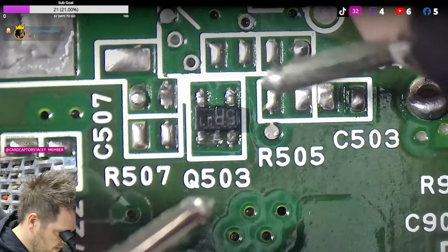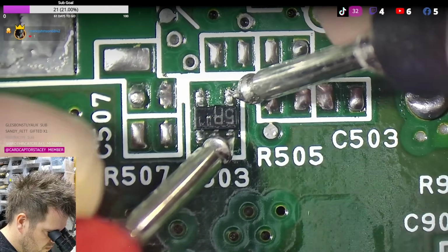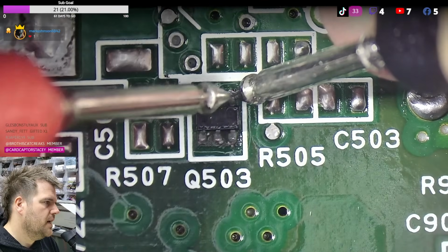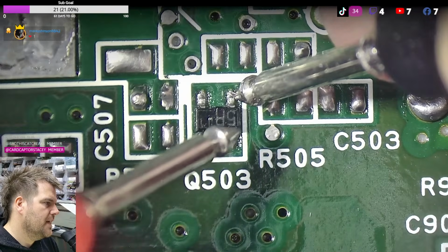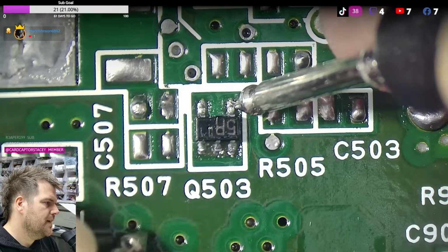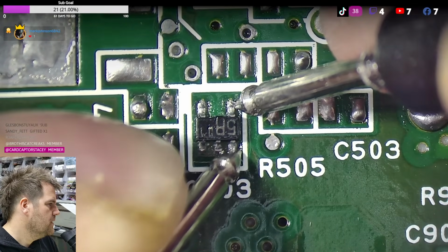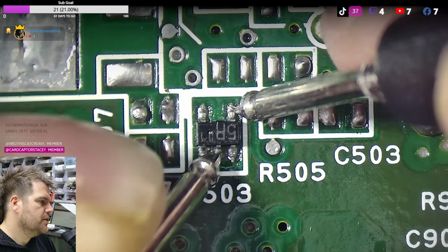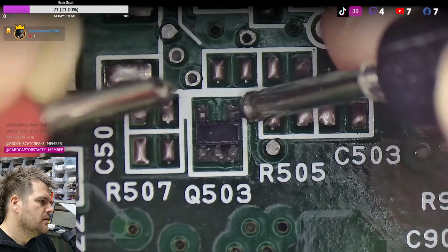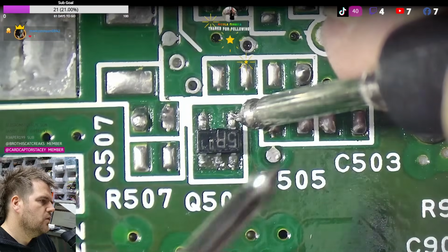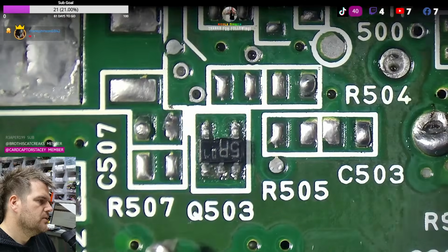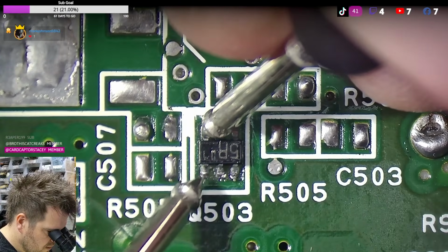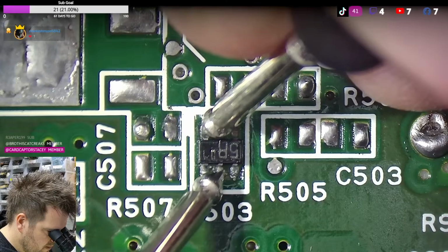So, now let's see. We did have a beep, I'm sure. There we go. So, there to there. So this is our cathode. This is an anode. So we have a diode in here. The fact it's Q, it's going to be a transistor. So we're going to have either an NPN or a PNP. We don't know which yet. So there's one there. So that's one. Let's try this pin, the other side. I wonder, this could be a Darlington transistor maybe. So there's an NPN there.